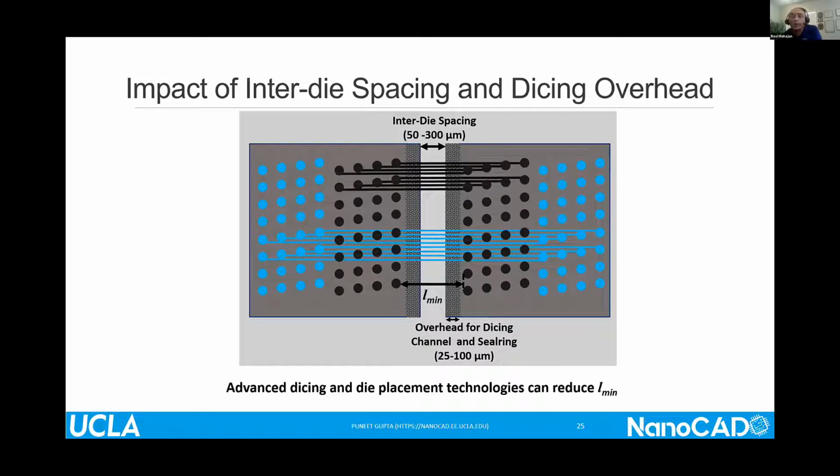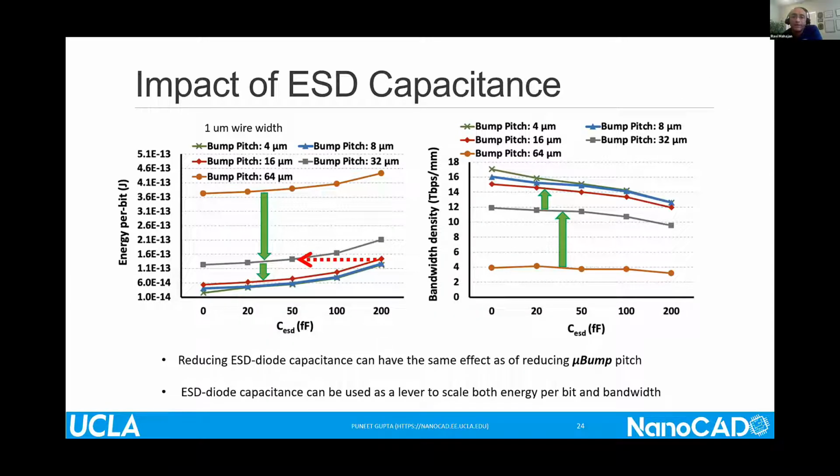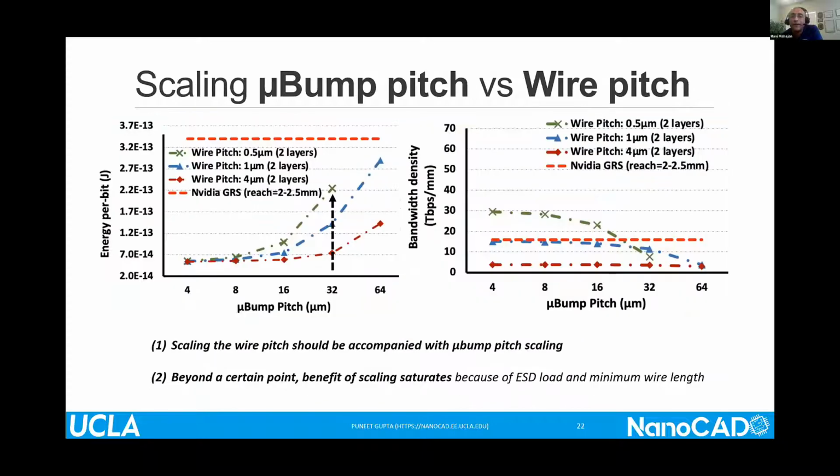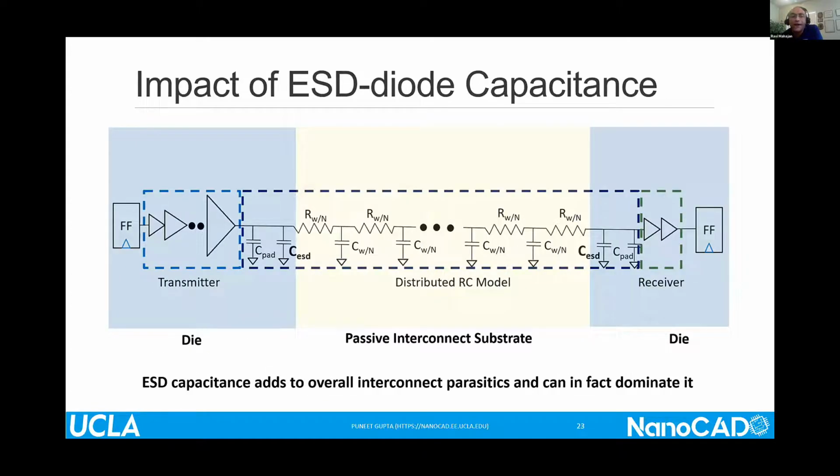So Puneet, 2 questions. If you go to that previous slide, maybe the one before. If I took a very, very high level view of power, what percentage of power is it in the transmitter, the receiver, as well as? Very little. Total, if you had 1 picojoule, 0.1 picojoule per bit. I don't remember the precise numbers, but percentages. The transmitter and receiver are not taking up bulk of the power. Your wiring plus ESD load takes up a lot of power here.